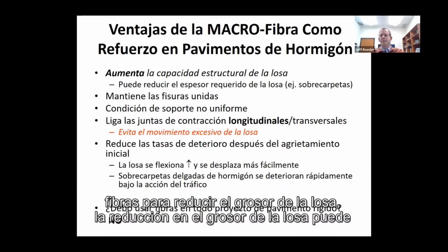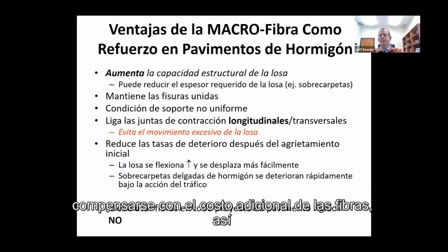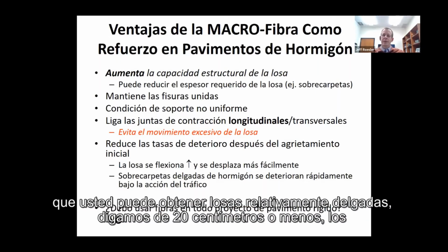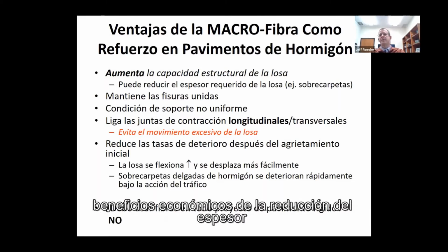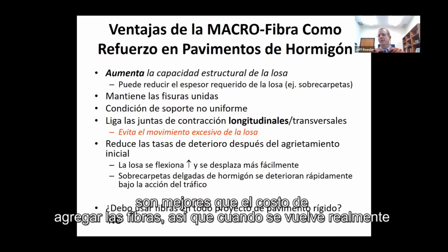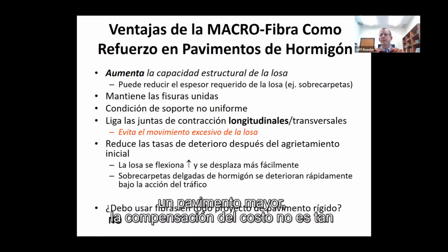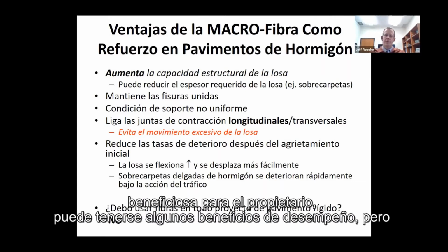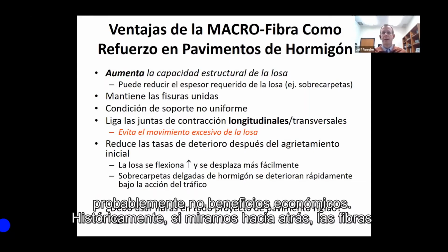My reduction in slab thickness may be offset by the extra cost of the fibers. As you get to relatively thin slabs, let's say 20 centimeters or less, the economical benefits of the reduction in thickness are better than the cost of adding the fibers. When you get really thick pavements, the cost trade-off isn't as beneficial to the owner. It may have some performance benefits, but probably not economical benefits.